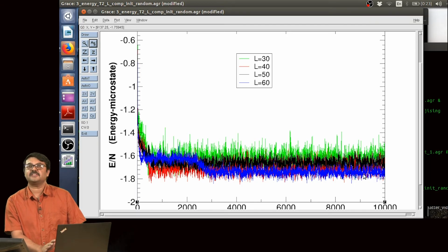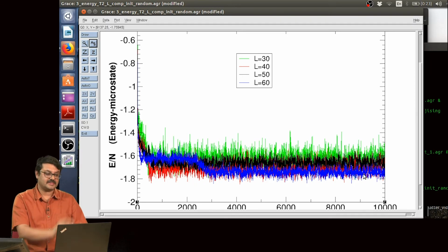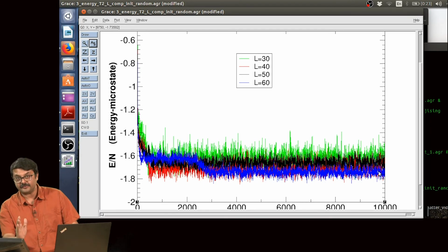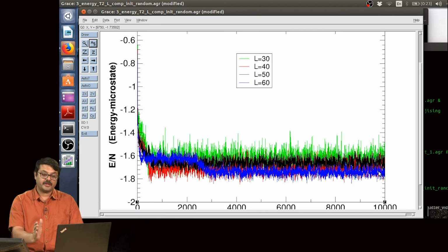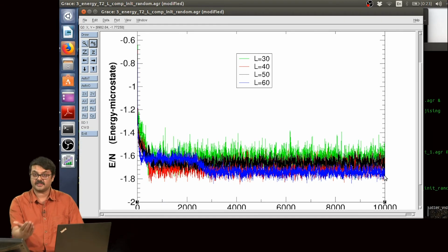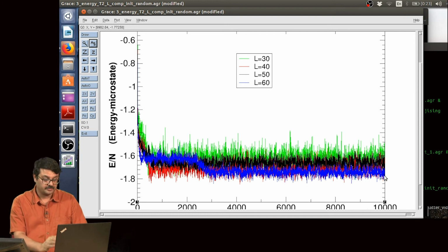Whether there is any further shift in the data or not, only after we are sure that the system has reached equilibrium, which means all these initial variations have gone and it keeps on fluctuating about an average value. From that point onwards, in this case maybe ahead of 10,000 iterations, we should basically check or collect data to calculate equilibrium averages and not before that.